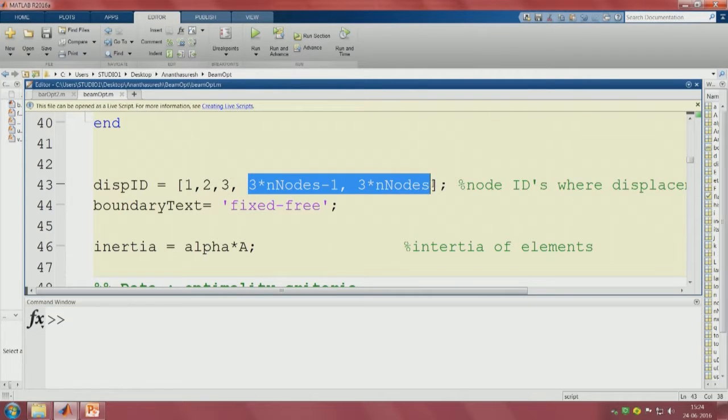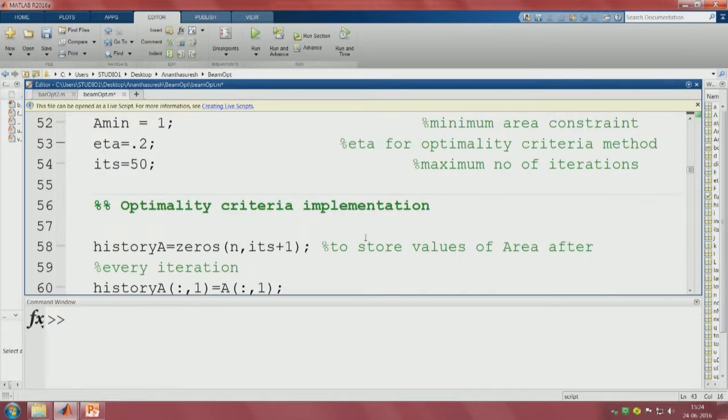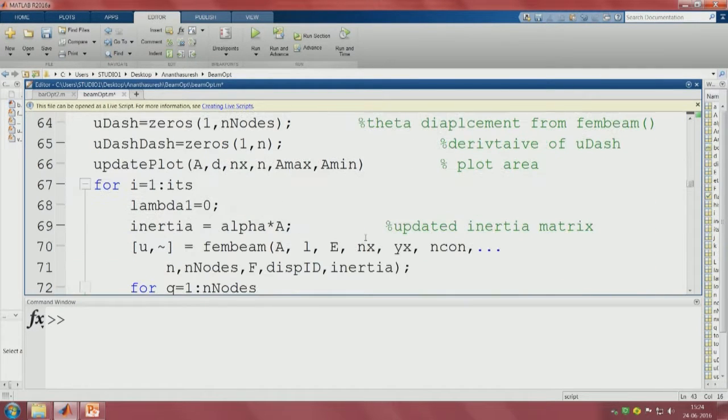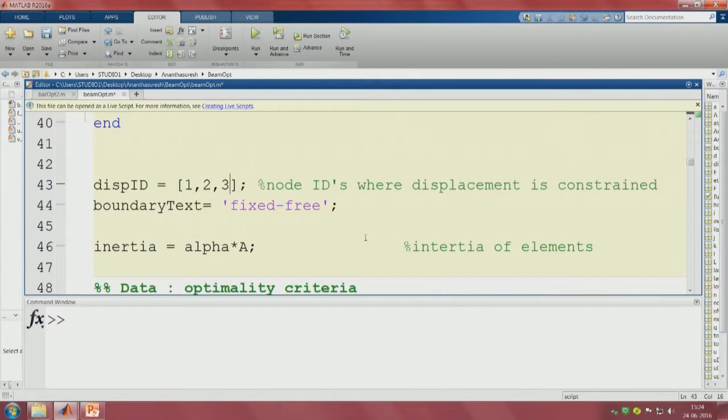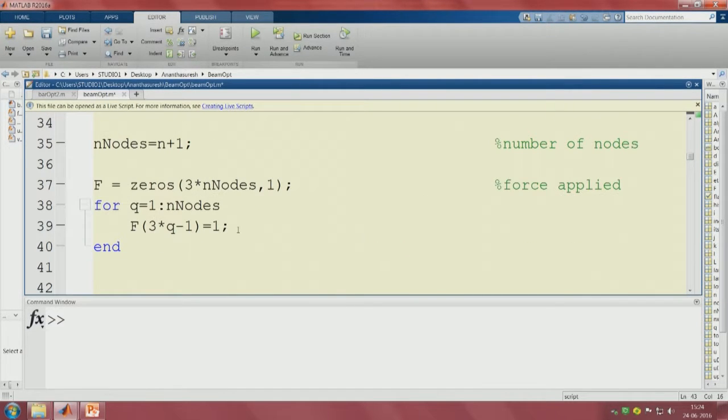Okay. So, we can run lots of them here. I can again go back to cantilever. Let us see how it looks when I change the loading to only point loading. So, let us see where the force is. Force is here. So, now it is force applied on all of them like 1. Okay. So, we can make it uniformly distributed or only at one node. Now, it is going 1 to 1 nodes, all of them it is giving,